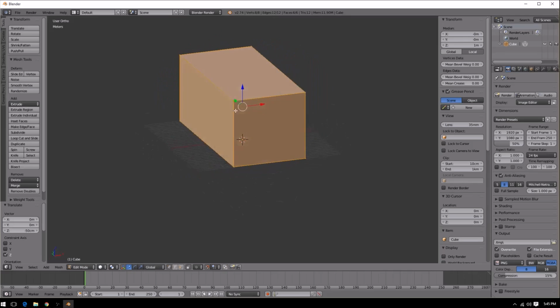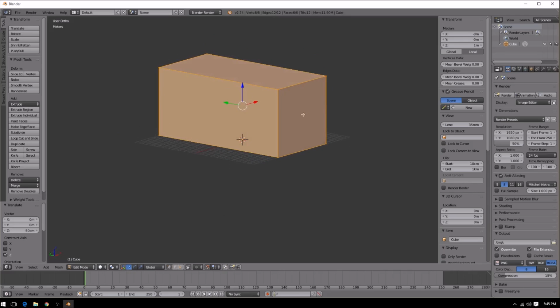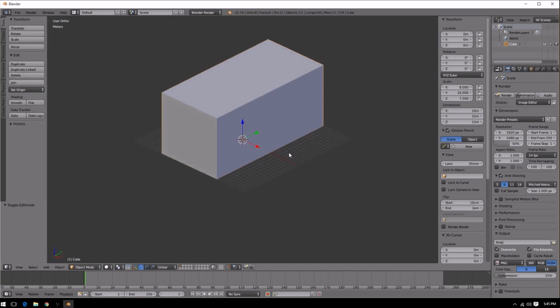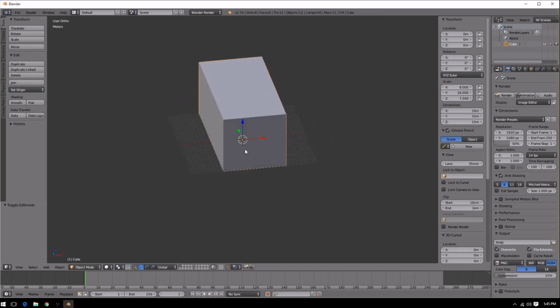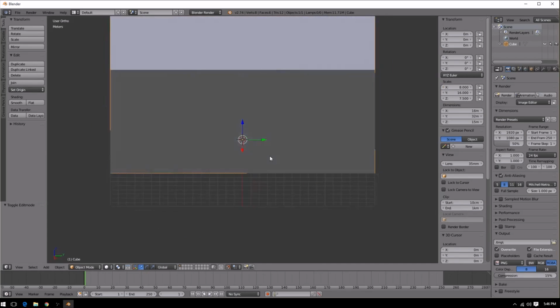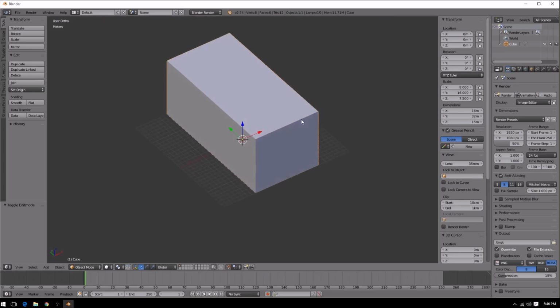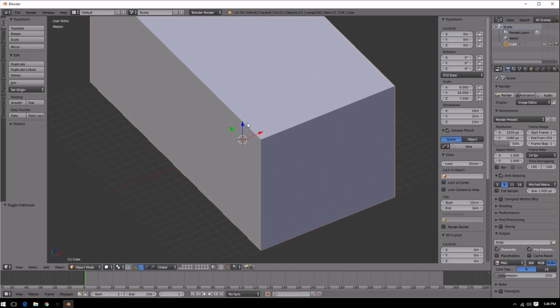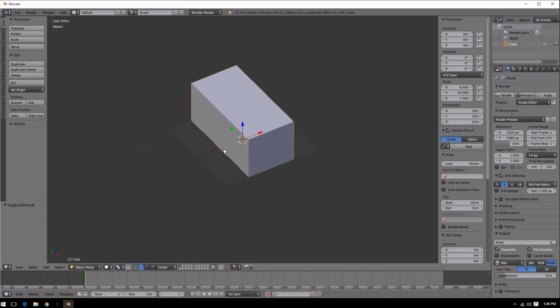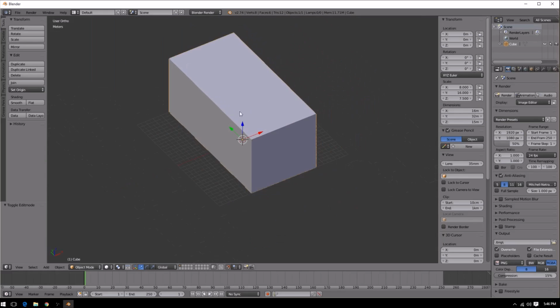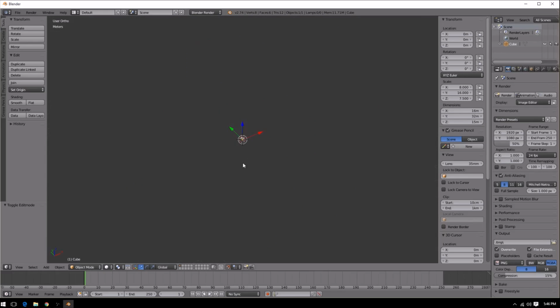Now, in this situation, this is going to be our LOD, or level of detail. And a lot of people do the LOD differently. There's not a right way or wrong way, as long as you keep to the basic tenets of what the LOD is, which is a very extremely low poly, far away view of your asset, so that it renders at a lower file size than all of your other meshes. The details don't need to be there on the level of detail. That's the name, because you are zooming in on a far away object.